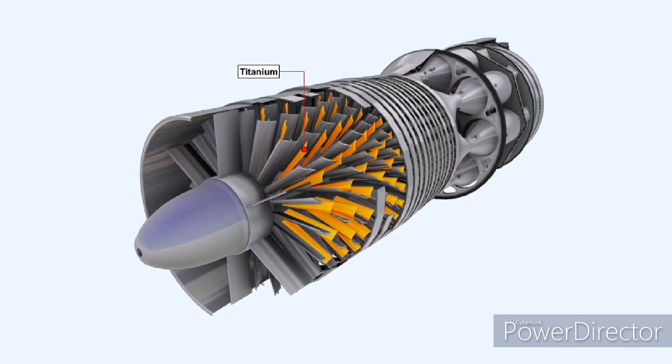Some of the low-pressure stages of the compressor, where the temperature of compression is not too high, may have their rotor blades manufactured from titanium. Indeed, as higher temperature titanium alloys are produced, these alloys are progressively displacing the use of nickel alloys in the rotor blades at the high pressure end of the compressor.